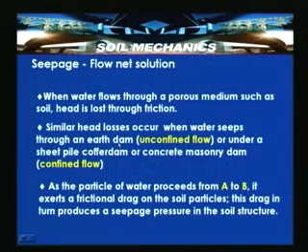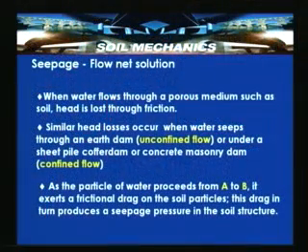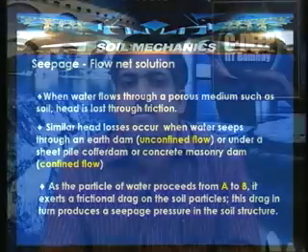That is an example of an earth dam; we discussed that as an example for unconfined flow conditions. And under a sheet pile coffer dam or a concrete masonry dam, the confined flow conditions can prevail.